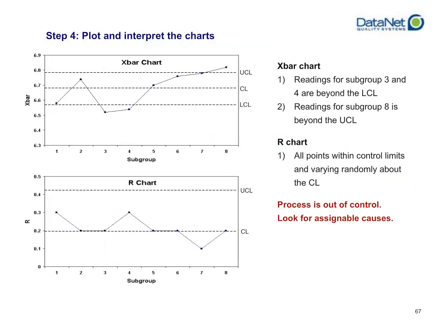Step 4 is to actually go and plot your control limits for both your X-bar chart as well as your R chart. You're going to plot your upper control limit, your center line, and your lower control limit for your X-bar chart, and that's the stuff you calculated in step 3 in the previous slide. You're going to also plot your upper control limit independently for your R chart, so that you can go ahead and begin to start plotting the items you calculated in step 1 for each one of the charts.